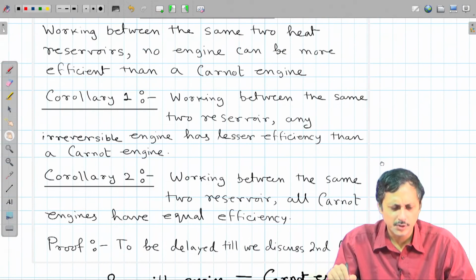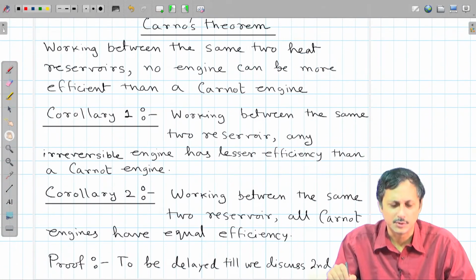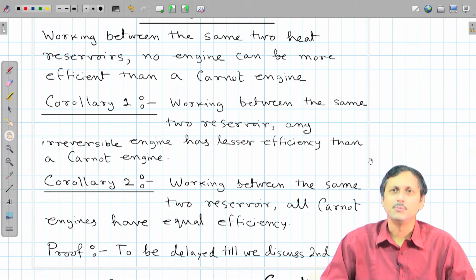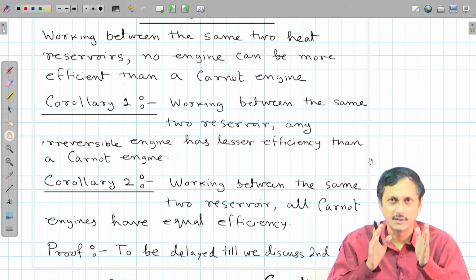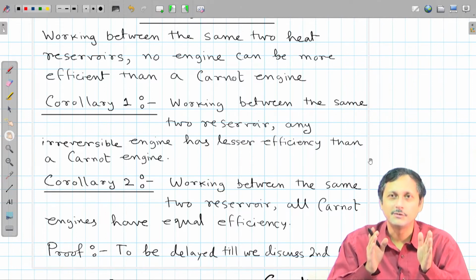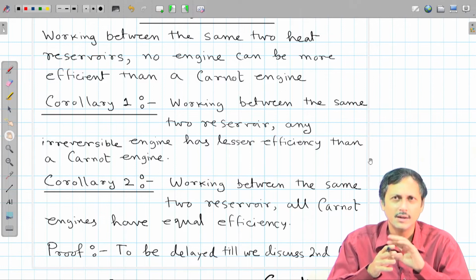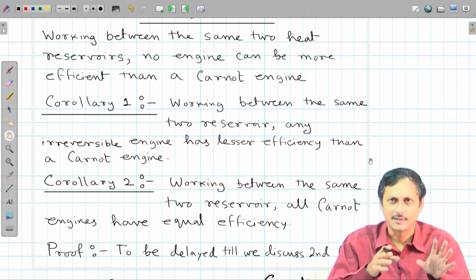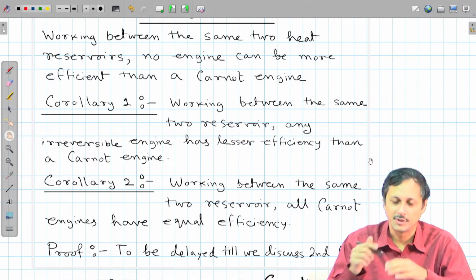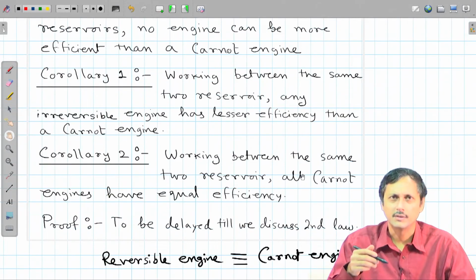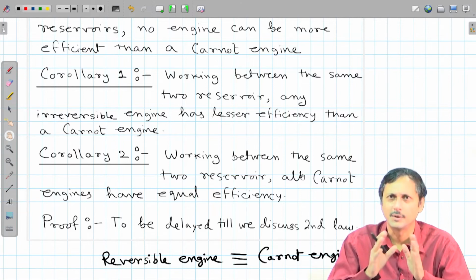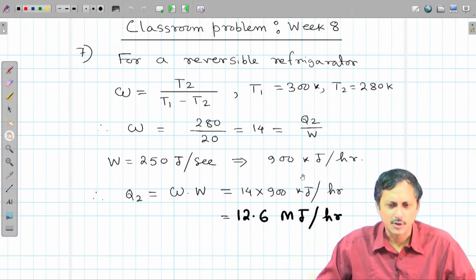But this Carnot theorem has implications, like if any experiment produces an efficiency more than the Carnot engine, given that you can define the source and the sink, we can blindly discard that result, because once again Carnot theorem is based on the second law of thermodynamics, and if we accept that Carnot theorem is not valid, that means we are not accepting the second law of thermodynamics. Okay. So, without further delay, let us talk about okay.